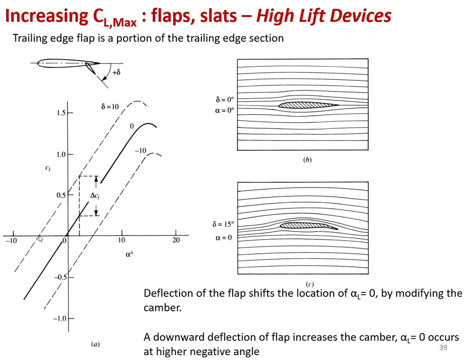Essentially it means that although with a trailing edge flap you will be able to get a higher CL max, you will also be hit by a lower stall angle, because everything has moved to the left. Essentially everything has moved in this direction, to up and left.